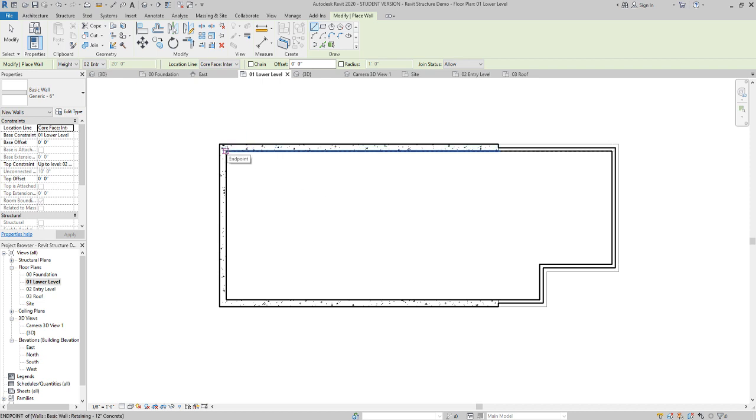So if I hover right here and then move, it starts to reference that center of that wall 26 feet over, and then they want us to go all the way down, straight down 90 degrees. Hit escape, click on line again. Probably don't have to hit escape this time because there's no chain on. And then we just kind of box out a generic area. So I'm going to go like 9 feet, and then I'm going to go maybe like 7 feet.